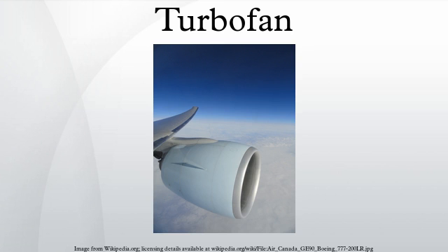The turbofans on twin-engined airliners are further oversized to cope with losing one engine during takeoff, which reduces the aircraft's net thrust by 50%. Modern twin-engined airliners normally climb very steeply immediately after takeoff. If one engine is lost, the climb out is much shallower, but sufficient to clear obstacles in the flight path.